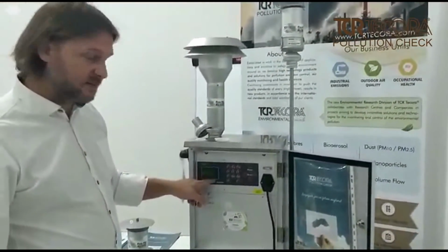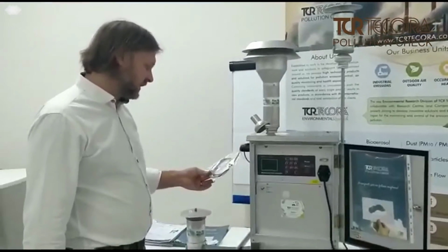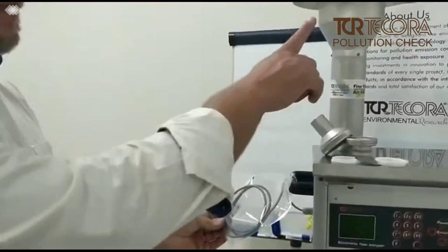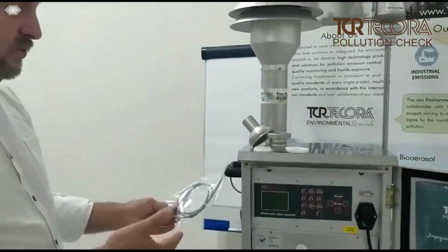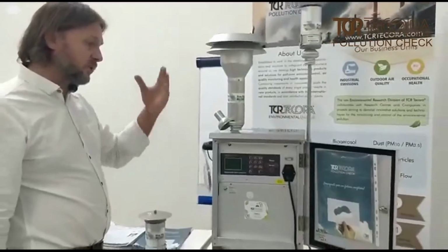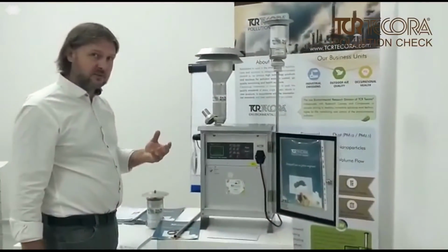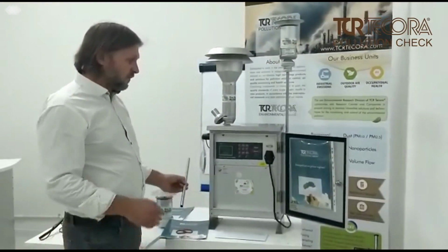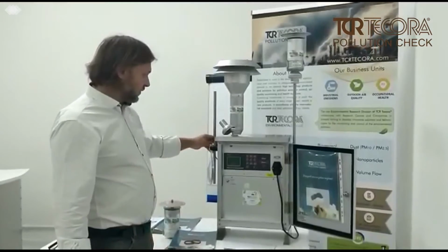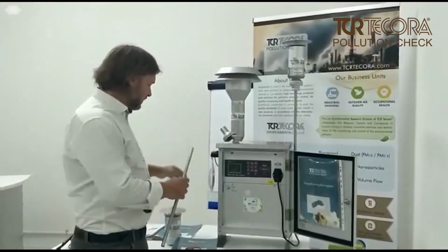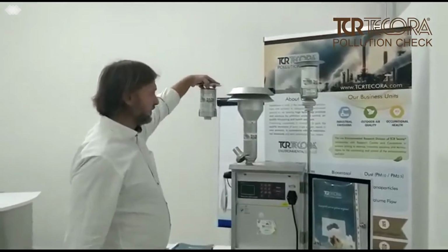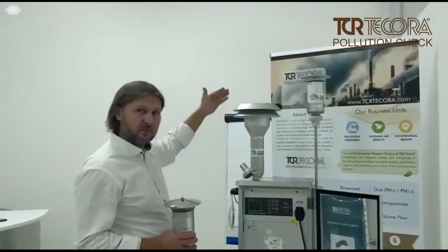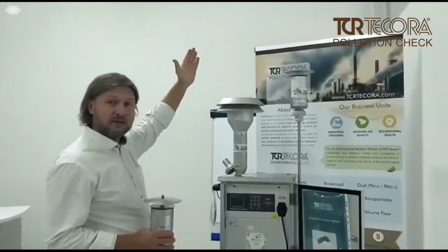Now it is 8%. Here in this bag we have our temperature sensor that normally is installed close to the sampling head, because we have to measure the actual condition in order to maintain the right flow. Just to tell you more than this, if you would like to make a double sampling, here you can install the second pipe with this head or with a head on this place. You can have a pipe with the length that you want, 1 meter, 2 meter, 3 meter, according to the point where you would like to sample.